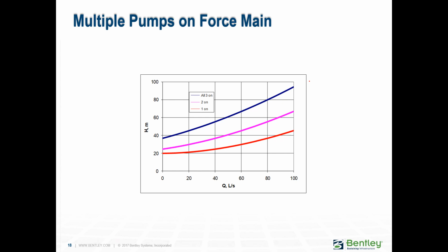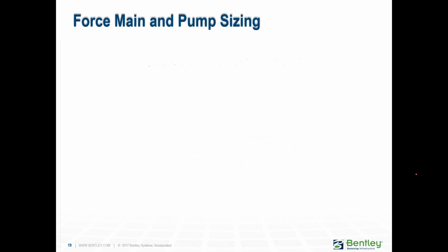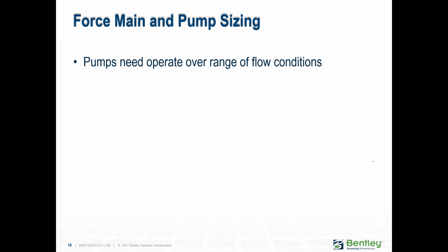And actually, you can do this kind of analysis in SewerCAD, and it's very neat, because you might find sometimes, surprisingly, that turning another pump on really does nothing, because if you're pumping through a very small diameter, the energy of that extra pump is all to fight the extra friction. So it's very important to do the analysis of the combination of pumps.